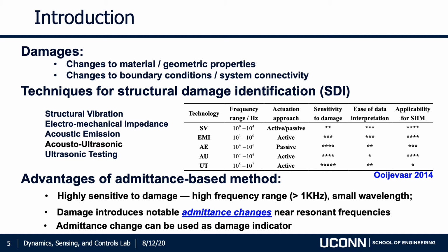And here in this research, we used admittance-based methods because it is highly sensitive to damage by using high frequency with small wavelength. And damage can result in admittance change around the resonance frequency, and this admittance change can be used as damage indicator.